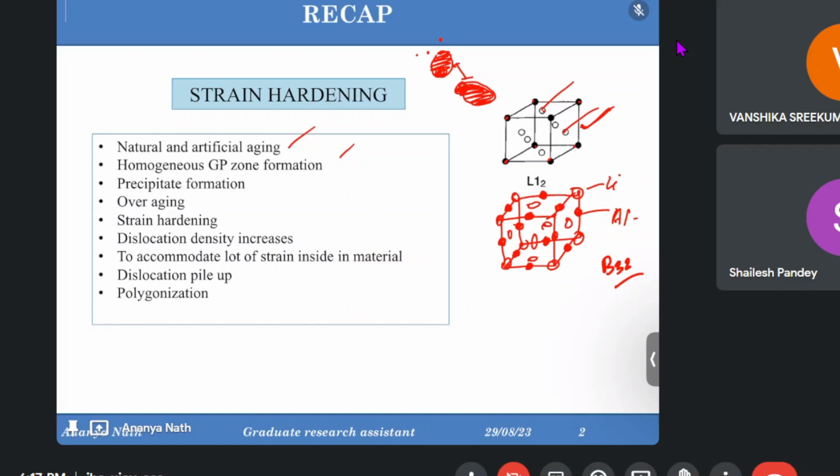So we do cold working like forging, extrusion, deep drawing or forming. These processes are basically done at room temperature, or sometimes at a bit higher temperature, but mostly at room temperature. This is why it's called cold working, and this is how by cold working the grains are stretched, and the dislocation density increases very much.